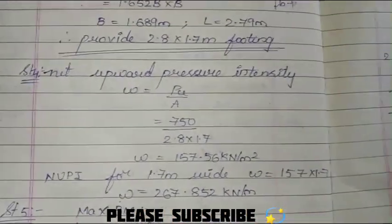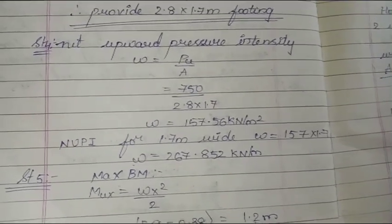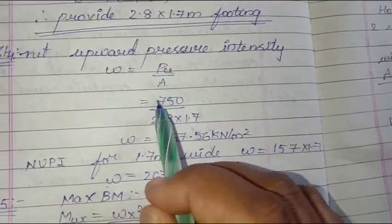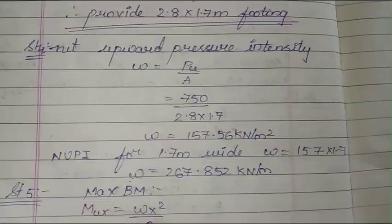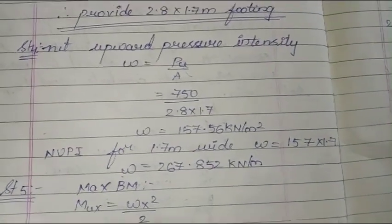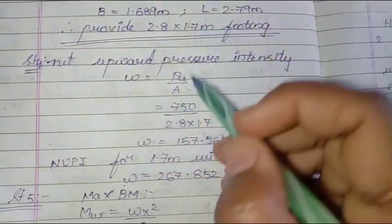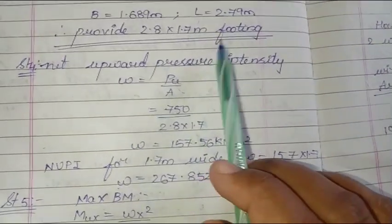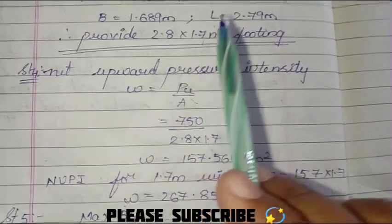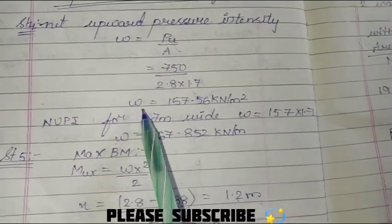Now we have to go to the net upward pressure intensity. Whatever the upward pressure from the soil has been exerted on the footing, now we will be calculating that. W is equals to PU by A. Here we know PU is nothing but the ultimate load, which we have calculated in step 1 itself, in the given data. Area we got now. So whatever the pressure that has been exerted on this footing, firstly we'll be calculating the dimensions of the footing. To that footing we'll be checking the pressure intensity. You'll be getting some W value.